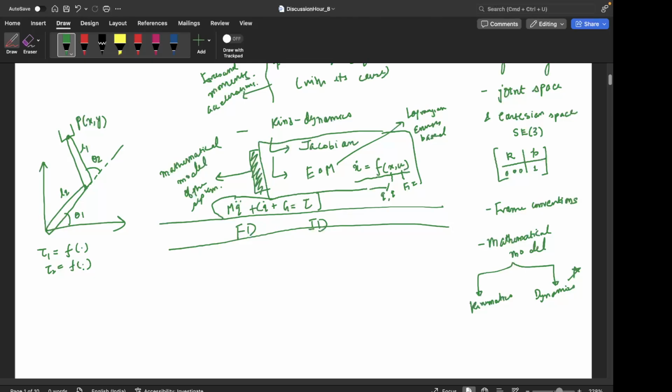This is the simplest two-link manipulator system. Now we will be concerned with, first, how we want to move our end effector in order to achieve a certain task. Because in each of the analyses that we have seen, we have taken a snapshot of the manipulator, an instant basically. Let's say an instant where theta 1 is 30, theta 2 is 60. We are not analyzing continuous motion as such till now. We have just analyzed the instantaneous configuration of the manipulator.